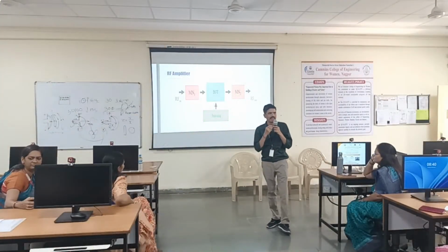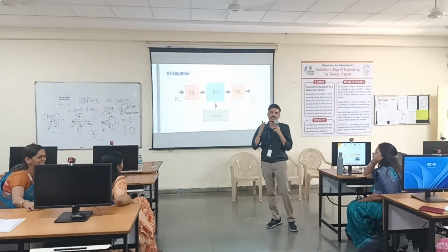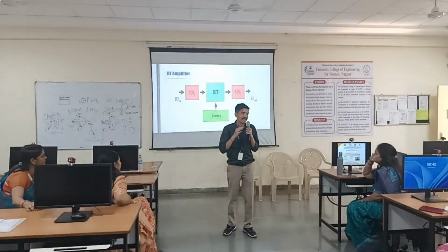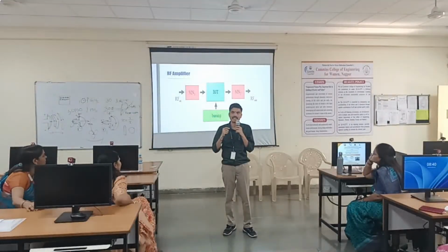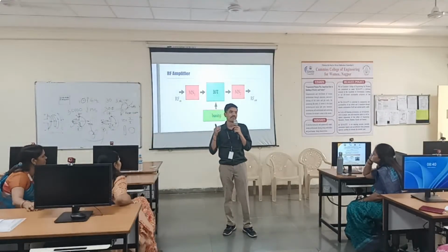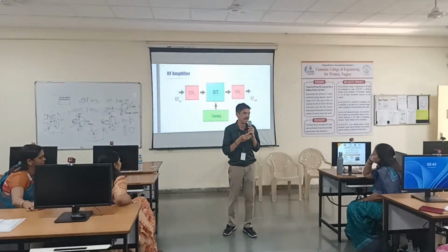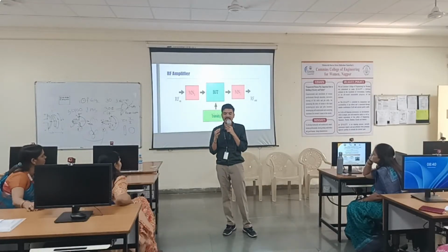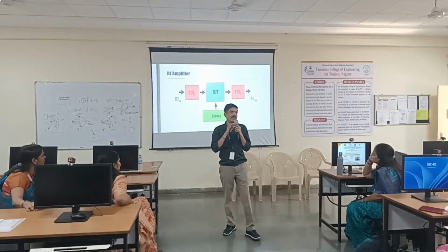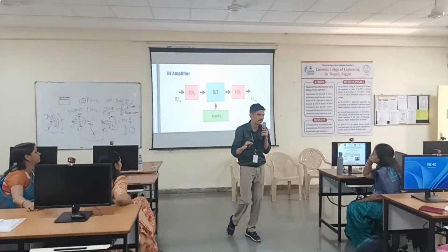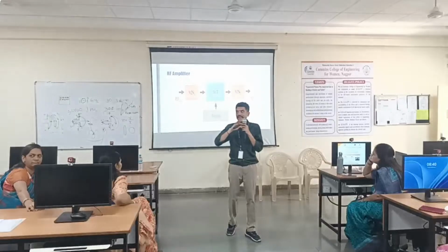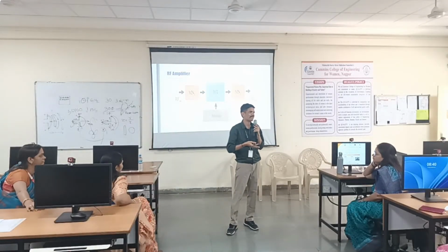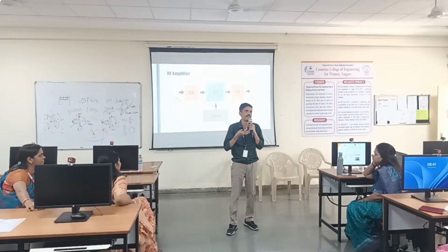So to tell you, see, PAs or amplifiers are too complicated. People used to say that if you want to design a PA, an amplifier, then you have to take a device, take a non-linear model, you need software, you have to do the load flow analysis, you have to do source flow analysis, you have to do the very tedious job of matching load flow design, then you have to go ahead and do the power sweep analysis, frequency sweep analysis, then actual PA design will start. After these many steps, actual PA design will start. What do I mean by actual PA design?